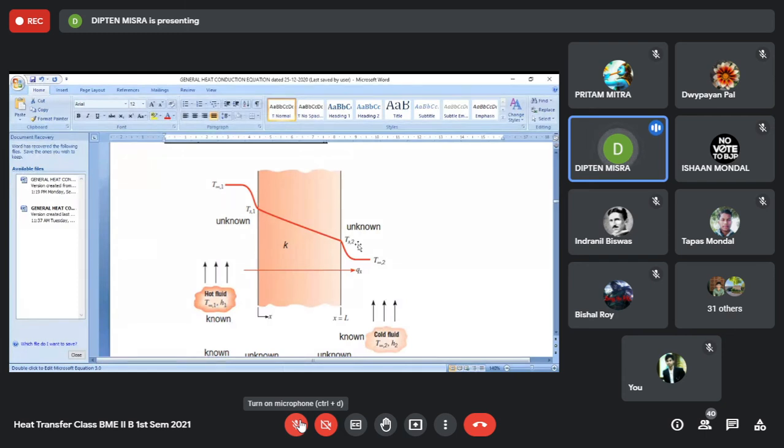Now, the outside walls are normally made maybe 10 inch, and the inside maybe 10 inch or 5 inch, and the inside wall, that is the wall in between rooms. You may have consecutive, adjacent rooms, and there may be a wall in between. That wall may be made of 3 inch. And the length of a brick is normally around 10 inch by 5 inch by 3 inch. You can orient the brick accordingly. If you want to construct a 3 inch wall, then you use that dimension.